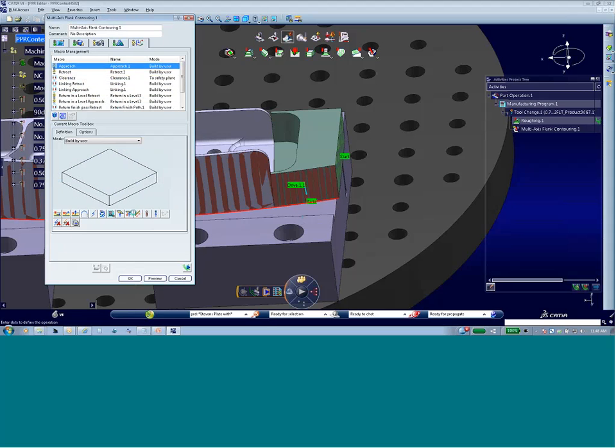Let's see, let's copy that as well. That was, what did I do? Oh, I was on a different one, wasn't I? Okay, well that's fine. I'm going to do the same thing here. I just did them backwards. Tangent in feed by a 1/2 inch, and a couple inches along the tool axis. That's what I meant to do. Similar for the retract.